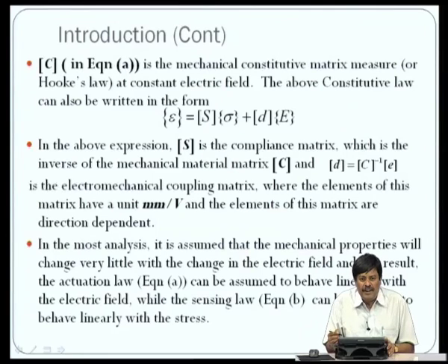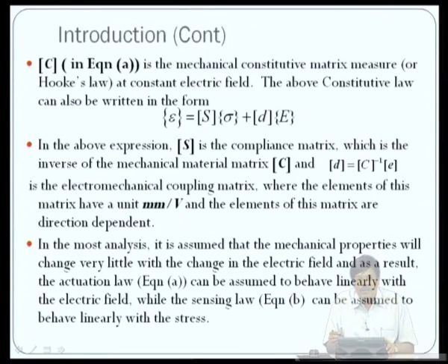In most of our analysis it is assumed that the mechanical properties change very little with the electric field, and as a result we can uncouple the sensing law and the actuation law. This is not true in the case of magnetostrictive material, which is highly coupled, but in the case of piezoelectric material it makes our life a little simpler, because these laws can be uncoupled since the mechanical properties change very little with the change in the electric field.